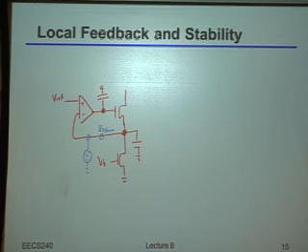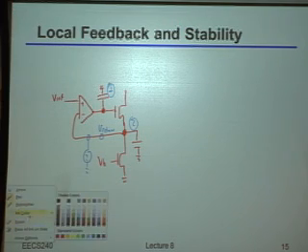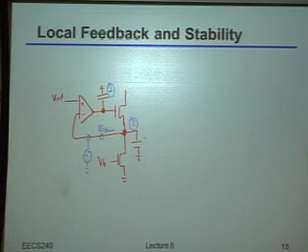So hopefully it should be pretty obvious that if I've done that, and at least if the ro of the transistor is infinite, I can only have 2 poles here, right? One pole, of course, is going to be from the amplifier. That's my first pole. And my other pole is going to be at that source node due to the capacitor that I added there. Let's label that capacitor, let's call that CX. So let's do perhaps the easier one first. Where is the pole due to that CX going to be? What frequency is that going to be at?